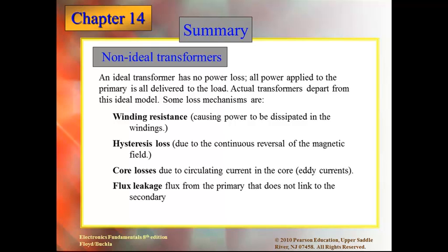Then flux leakage, talking about the magnetic flux lines. Not all of the magnetic flux lines from the primary, where we're providing power, go into inducing current in the secondary. Any of those magnetic fields that are lost are considered flux leakage.